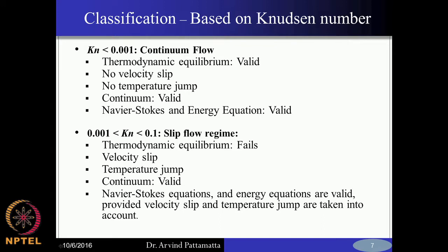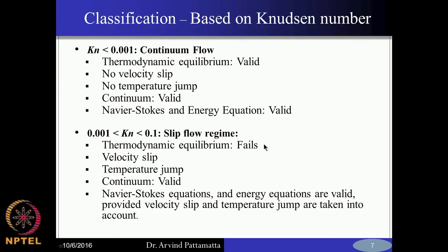Okay. So the continuum assumption is valid. However, the concept of local equilibrium will not be satisfied everywhere, especially close to the walls. This is where the scattering of molecules with the boundaries happens, and even at Knudsen numbers of the order of 0.1, the scattering between the gas molecules becomes more rarefied compared to the boundary scattering, and therefore locally near the boundaries there will be a non-equilibrium. So the thermodynamic equilibrium concept will not be valid throughout the fluid domain.